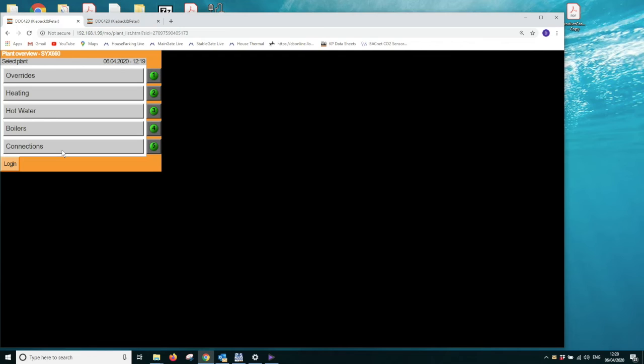Make sure that thermostats for underfloor heating systems are set to a set point which is greater than the set point that the optimizer is looking to achieve. We cannot have a thermostat which is set below the target room temperature of the optimizer. For obvious reasons, the optimizer needs to be able to achieve its target set point.